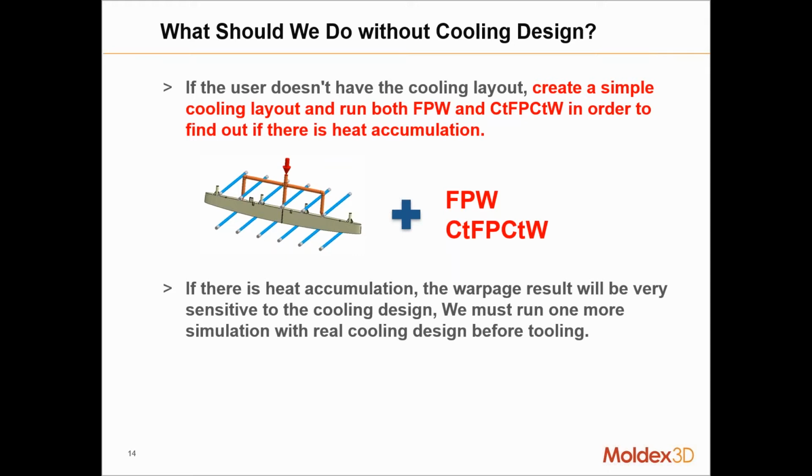And the other thing that this will help you identify is where the hotspots for this design are. And when you pass this on to your tooling engineers or suppliers, you are able to already point out where those potential hotspots are and where there needs to be good cooling.